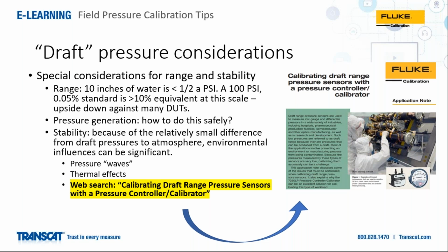An example of something that's really, really simple to do that they do down there in the lab is take a sheet of bubble wrap material, go to the shipping guy, steal some bubble wrap, and put it across the top of a bench top on pressure lines. What this does is help deflect and insulate drafts from the air conditioning system from influencing the pressure for low pressure or other sensitive calibrations. So it's a really simple way to do it that is really easy to achieve.